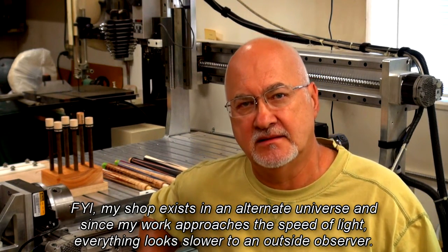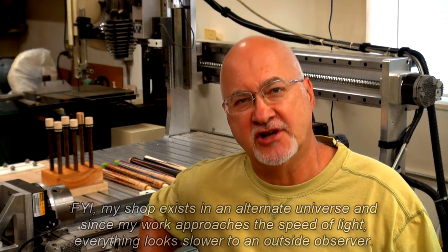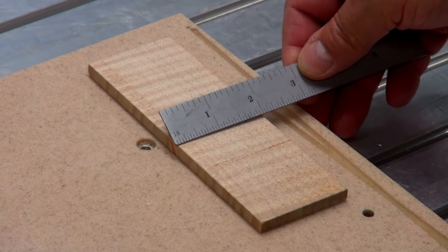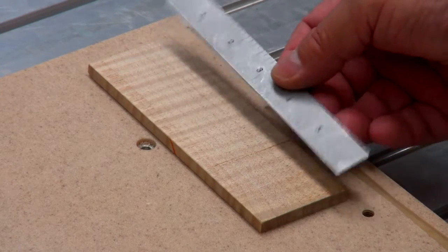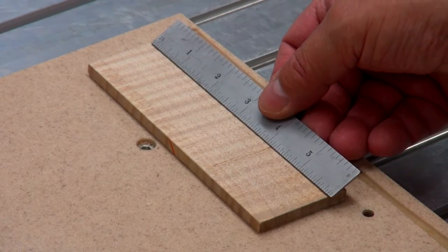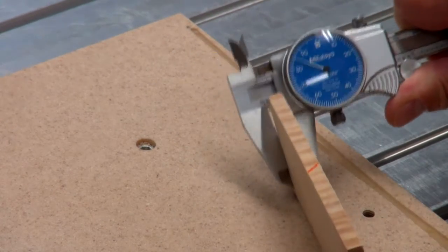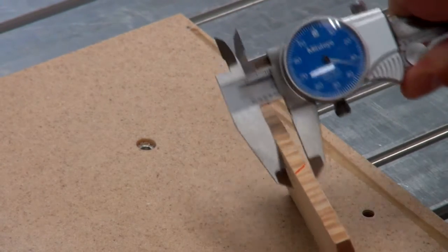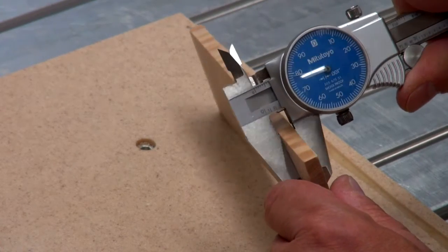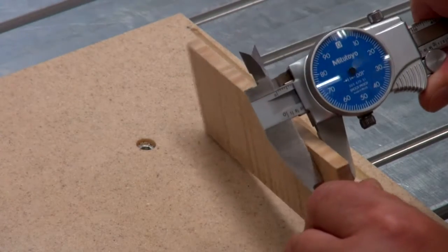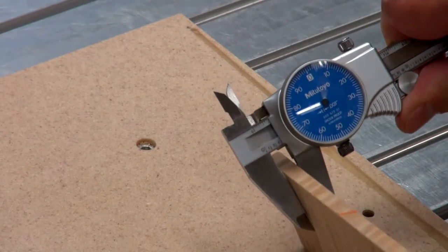I think it'll help if I walk you through cutting a slab to thickness and then cutting the strips from the slab. So let's get started. Okay, here I have a slab of curly maple that measures roughly 2 inches by 6 inches. I need strips that are 175 thou thick. This slab was cut on a bandsaw and measures roughly 280 thousandths thick. That makes it about 110 thousandths thicker than what I need, and it'll have to be cut down.